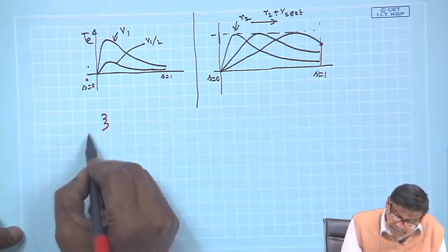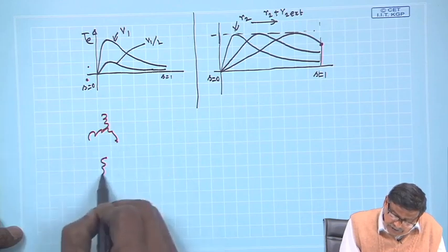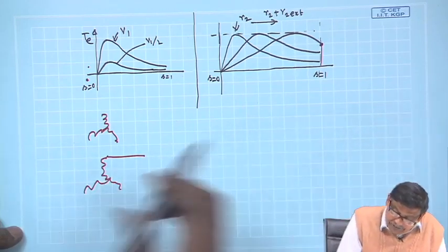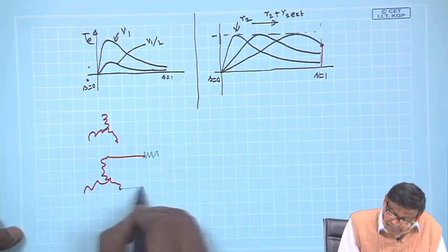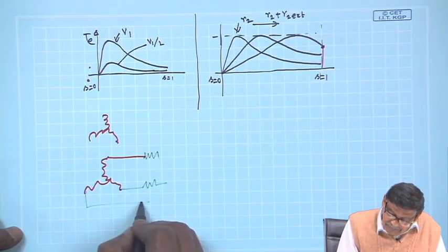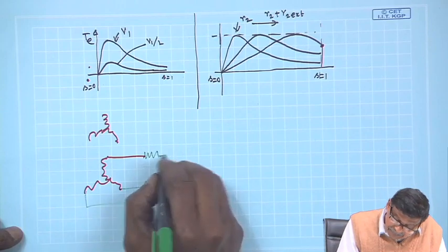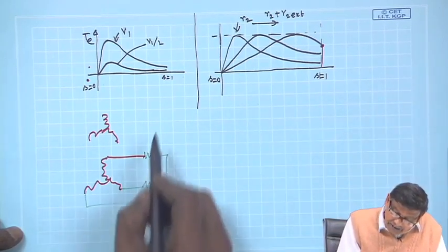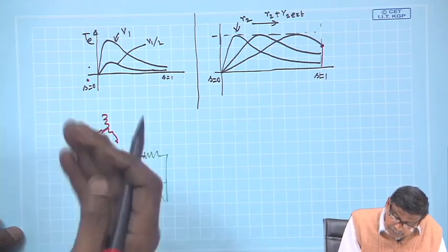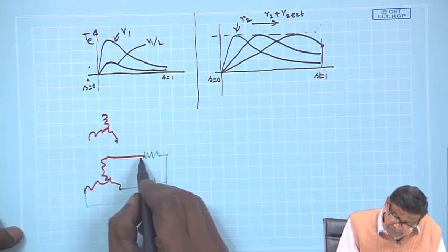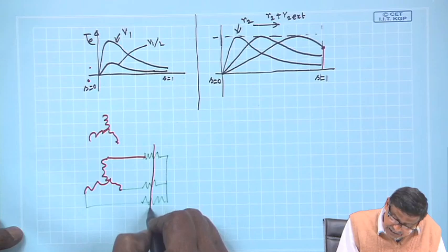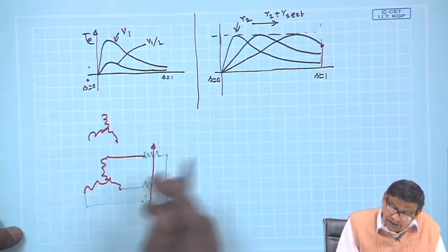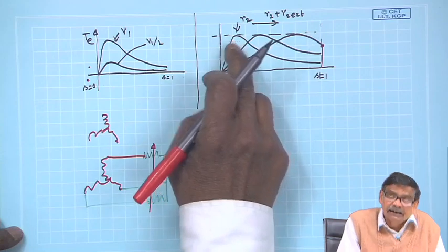This is stator. Let us draw it. What I was telling, you connect that R external, here, short it, some are external, but as the machine picks up speed, finally, that is why I showed it variable, bring it down to 0. So, that finally machine will operate at R2